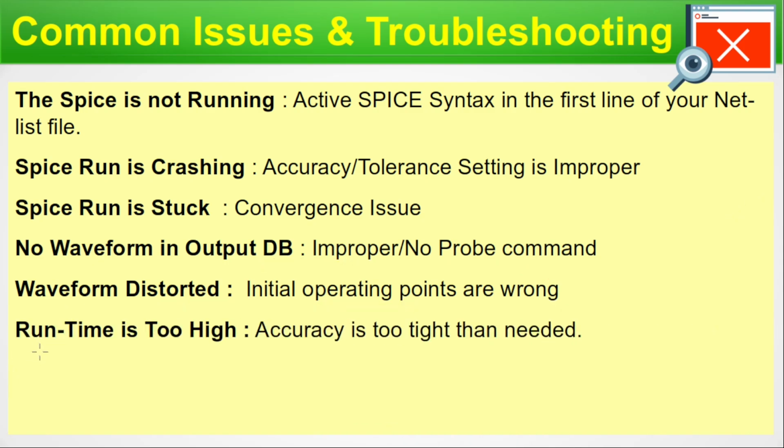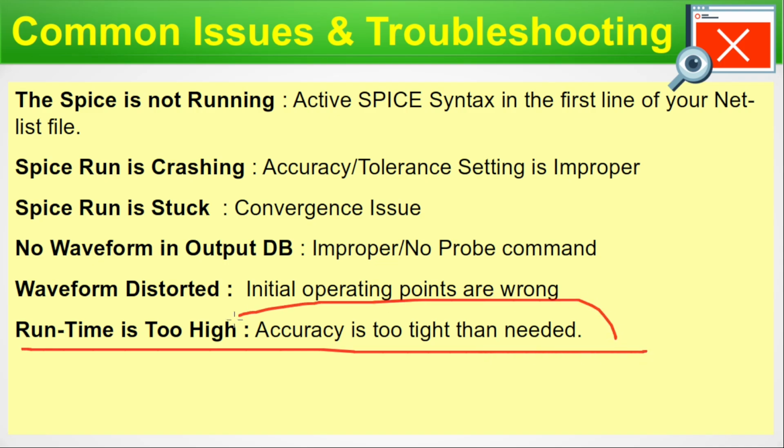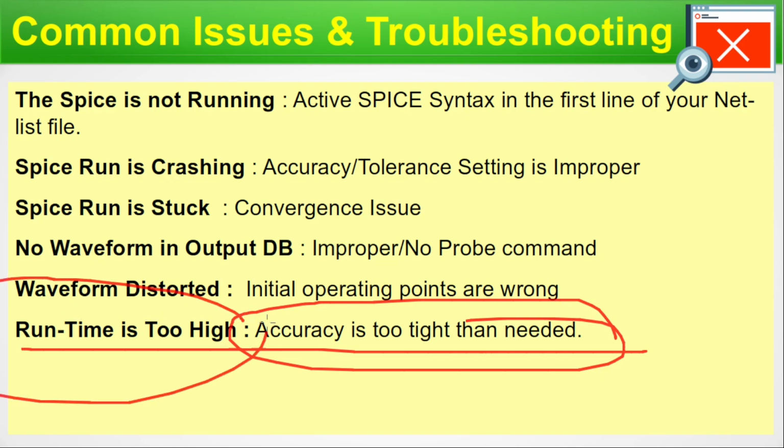Runtime is too high. The accuracy is too tight than needed. So accuracy here, first of all, is very much tightened. That means you are running a very high accuracy SPICE simulation. At that time, runtime can go too high.